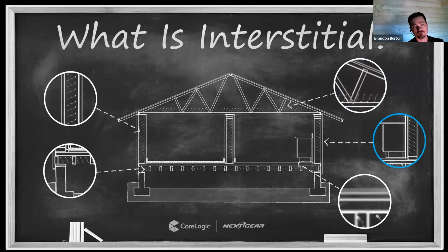You may even have, on the back side of the cabinet at the bottom, so very lower right-hand corner behind the cabinets, another entirely separate interstitial cavity and void, which is behind the counter, or cousin to the toe kick, right? So the framing members on the back side. So lots of interstitial cavities can be created by cabinetry and built-ins, depending upon how they're constructed.